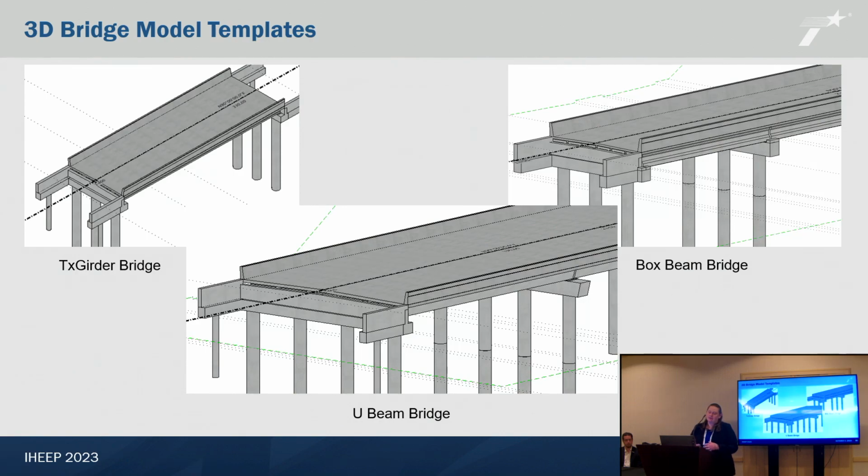The other place where this is used is for the roadway designers, because when you're doing the bridge layout, you don't have the bridge design, right? You've got generic things in there. And instead of using ORD templates or something like they're doing now, we're like, here is an OBM template, reference it into your roadway file, and then cut your sheets. That way, from the very beginning, we've got a 3D project, including the bridge. Even if whatever bridge they reference in isn't exactly what it's going to be at the end, at least they have the 3D bridge in there.